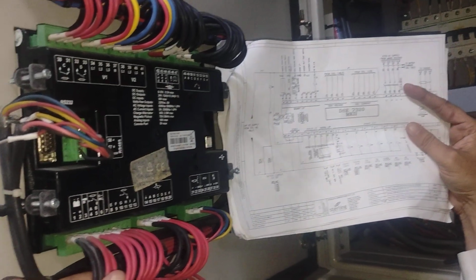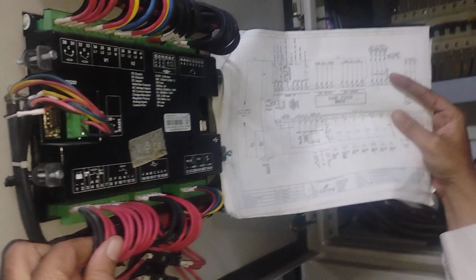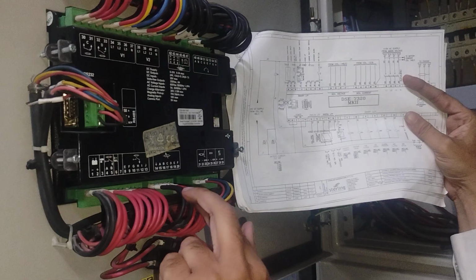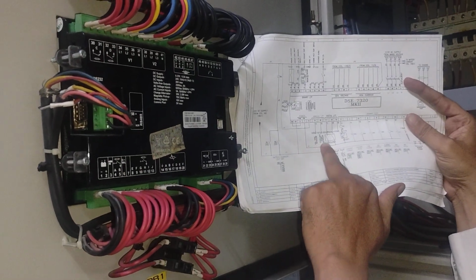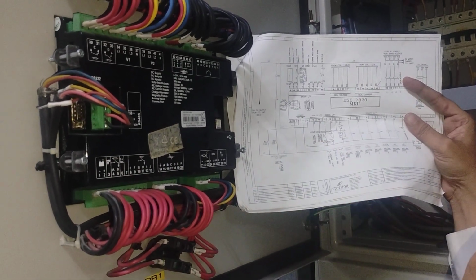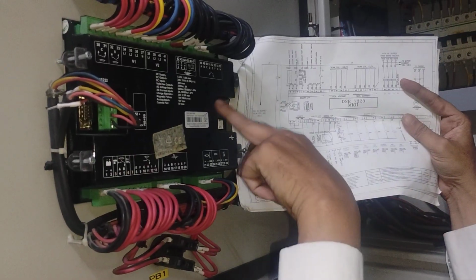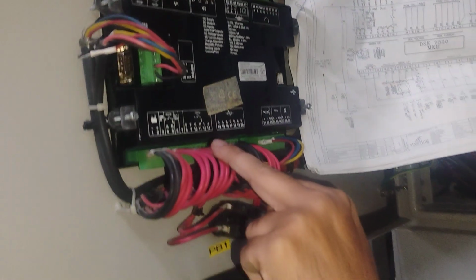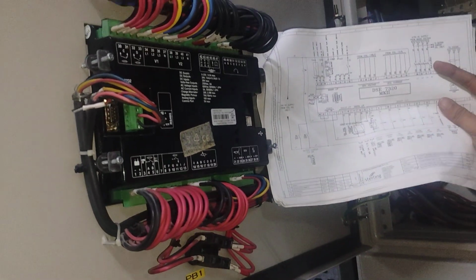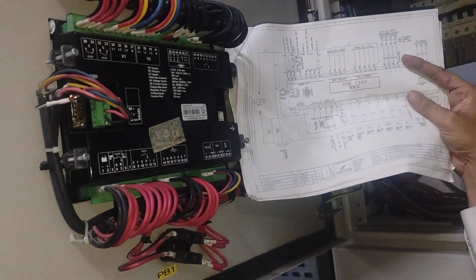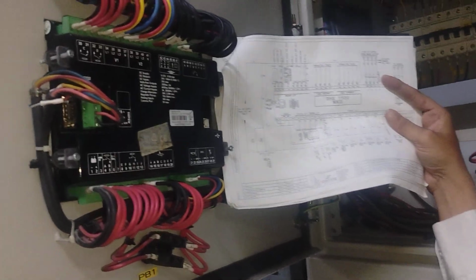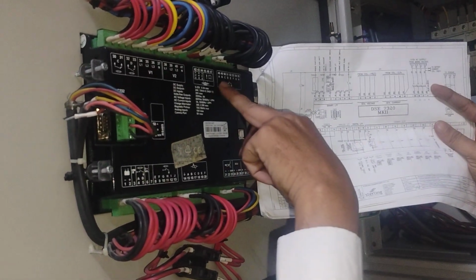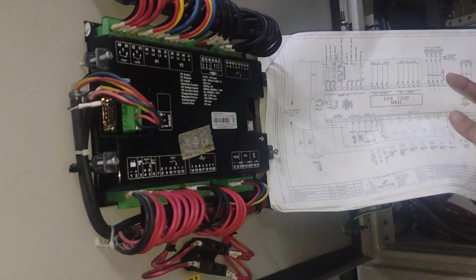These are the power supply for the controller to charge up. Thereafter various analog inputs like VDO 10 bar, PT100, and various other analog inputs, and various digital inputs are here. In digital input we can get the oil pressure switch, coolant level switch, and oil pressure switch. And in analog we can get the VDO 10 bar, PT100, and the rest of the other analog inputs.